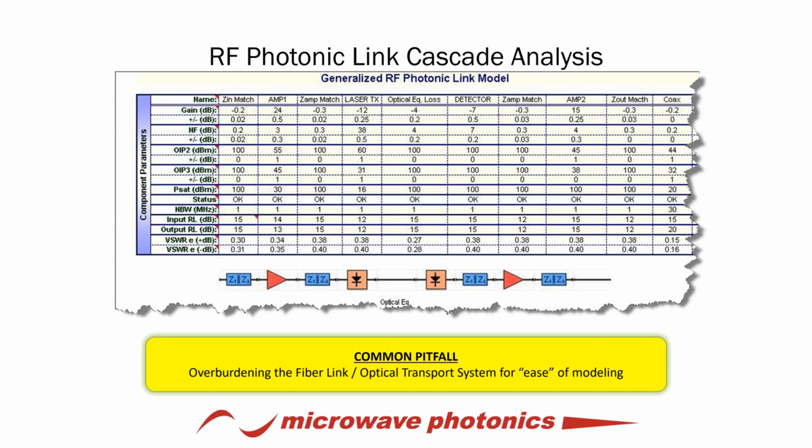And what I mean by that is either setting an unrealistic requirement for noise figure or simply defining the link as unity gain. Now, we sell many links and I've seen many solutions where it is unity gain, but if you're versed in traditional RF and microwave engineering, you've got to get it from somewhere. So what I suggest is when you map your system, if you're transitioning to, let's say, a 20-kilometer system, well, I challenge you to find a 20-kilometer piece of coax that's unity gain.